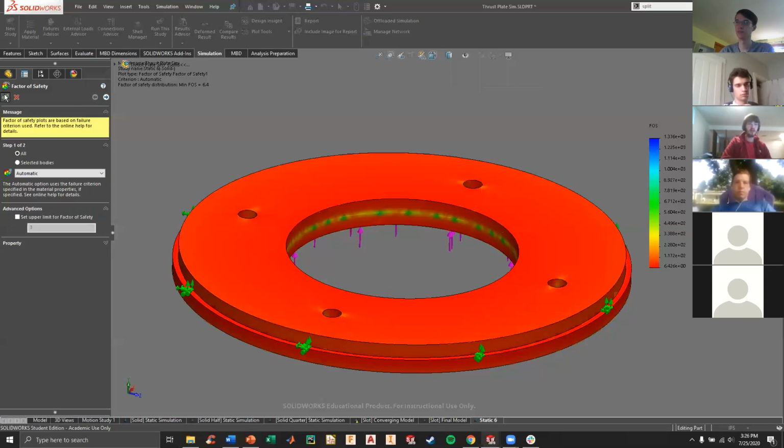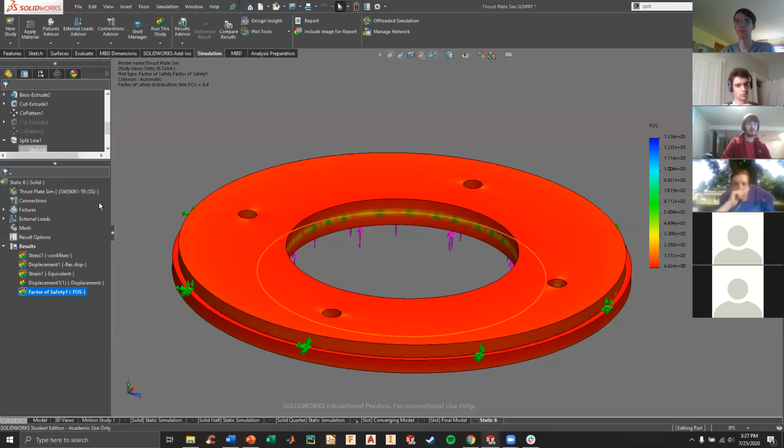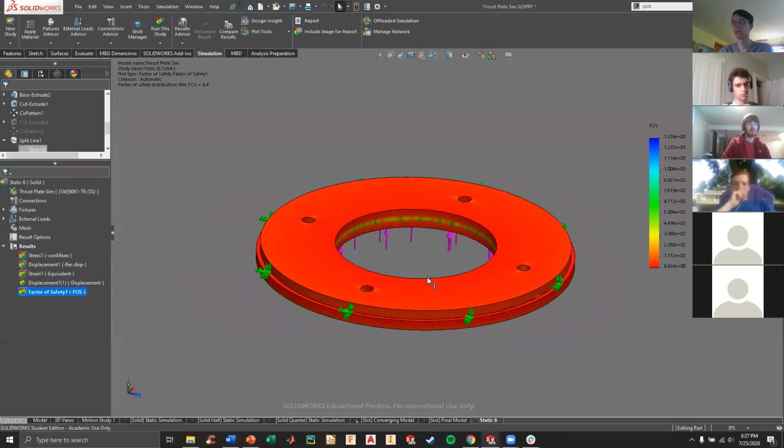The key thing though is that it just goes until it starts plastically deforming. Yeah, so you can actually take linear static models beyond their yield point. They just stop being accurate after that. So you can do a simulation with that, and if you see it, then you'll have to go back and do a nonlinear study to actually figure out if it's going to deform like you think it will, and if it will fail due to that deformation.